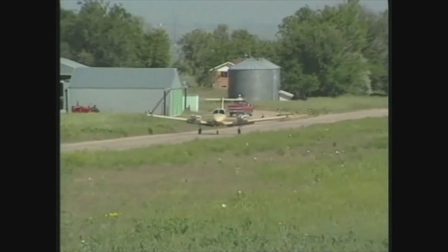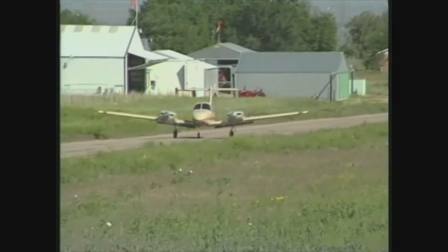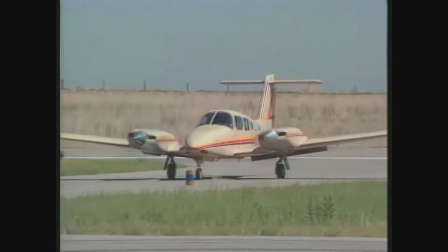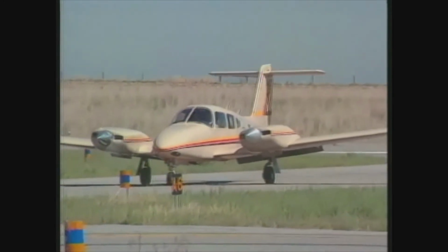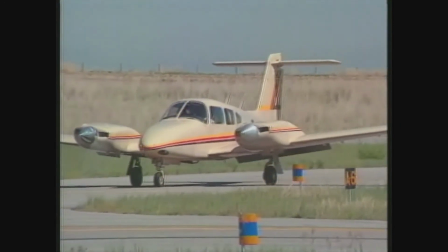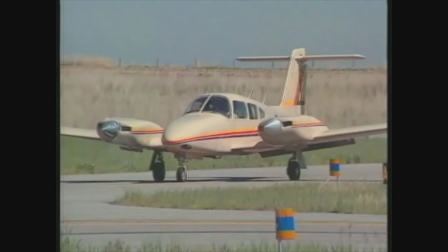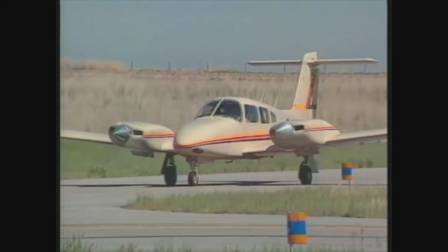Elevator back pressure improves braking action by putting more weight on the main wheels. If absolutely necessary, the flaps may be raised for maximum braking. However, if landing distance is not a factor, wait to accomplish the after-landing check until you're off the runway and can concentrate on activating the right controls. Raising the gear handle instead of the flap handle could be as expensive as it is embarrassing.